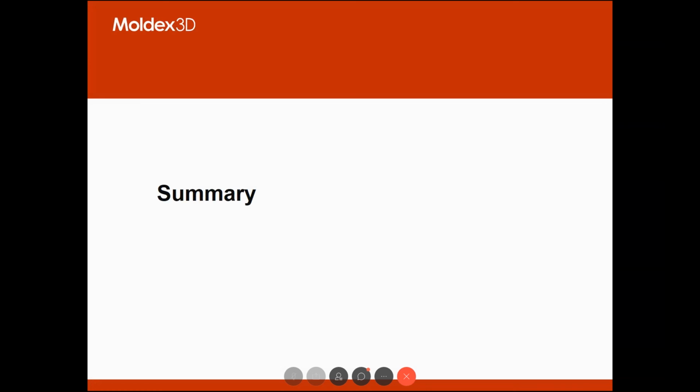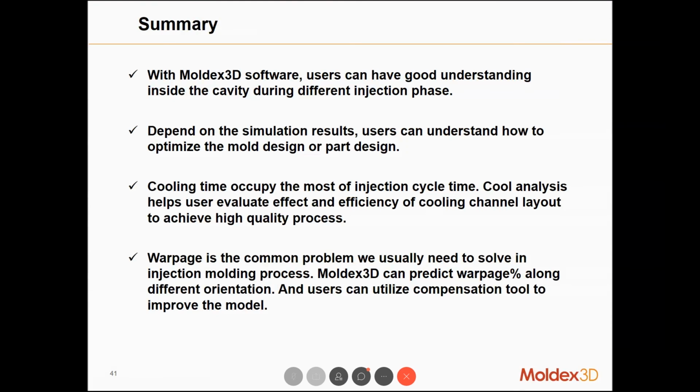Okay, so here's a summary. With the Moldex3D software, users can have a good understanding of what happens inside the cavity during the different injection phases. And the second one is, depending on the simulation results, users can understand how to optimize the mold design and the part design. And the cooling time occupies most of the injection cycle. So cooling analysis helps users evaluate the effectiveness and efficiency of the cooling channel layout to achieve a high quality process.